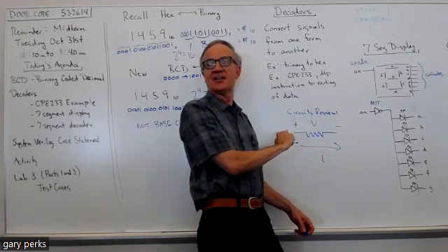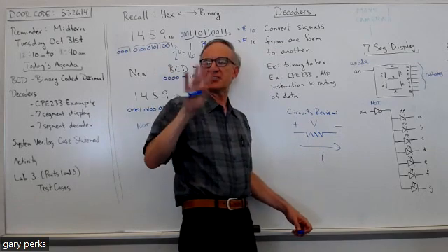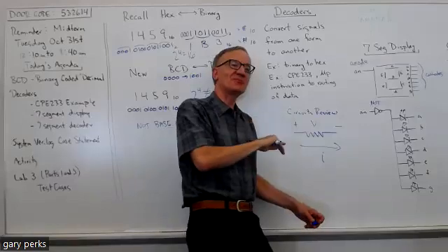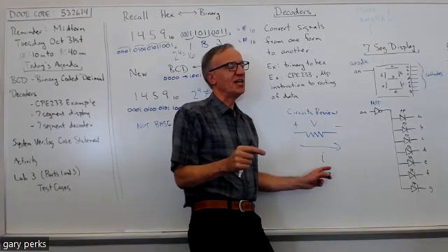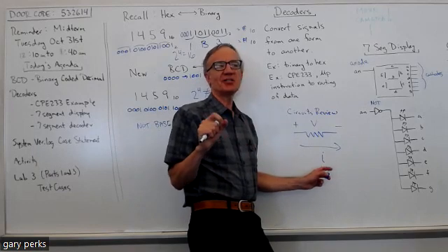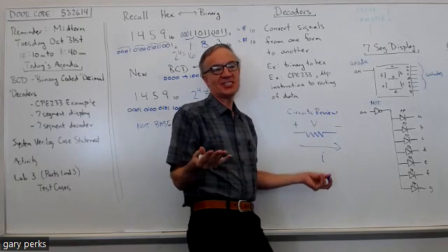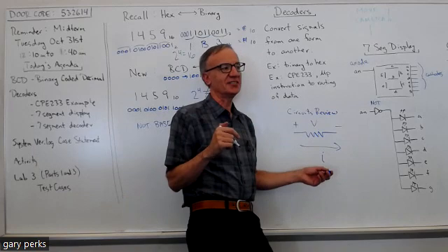Well, you can have multiple resistors and have a voltage divider. That's a type of circuit. But there's voltage rises and voltage drops. You get a what across a resistor? A voltage drop. And when you have a voltage drop, is energy being absorbed or supplied? Absorbed, right? Because a resistor can't supply energy. They can only absorb energy and they dissipate it as heat.